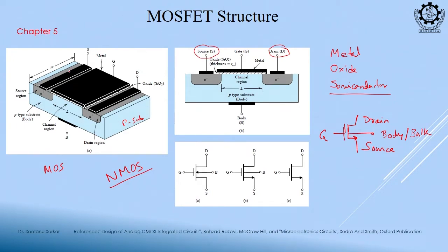So, these 2 symmetrical junctions, one is our source, one is our drain, and in between source and drain, this length we call our channel length. This channel which is forming between source and drain, that we will term as the channel. Actually our majority carriers will flow here.